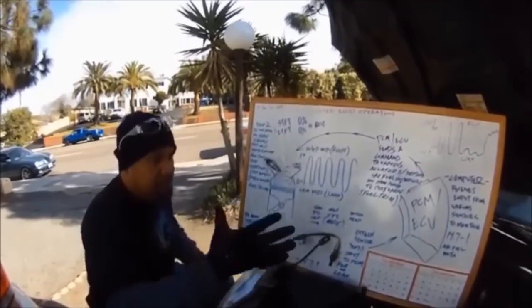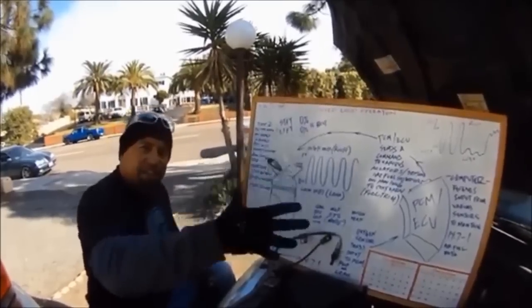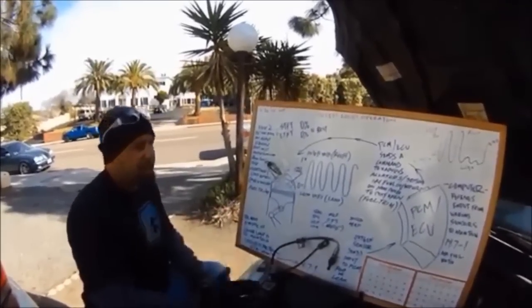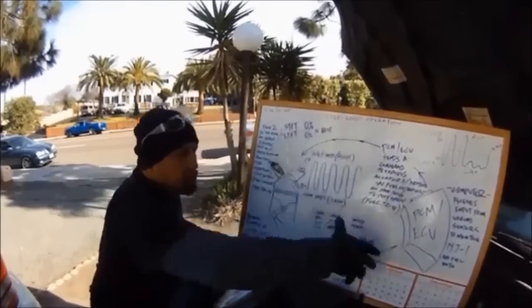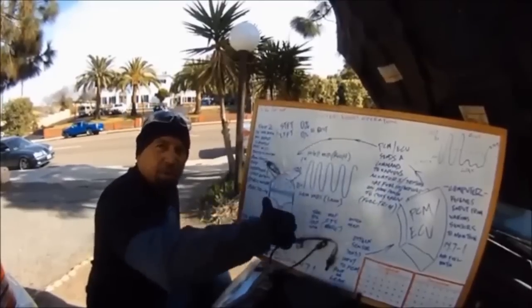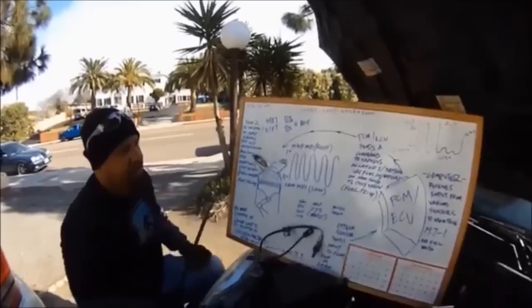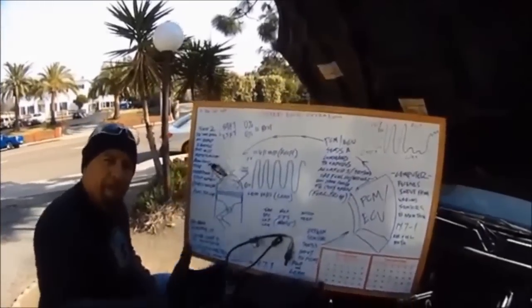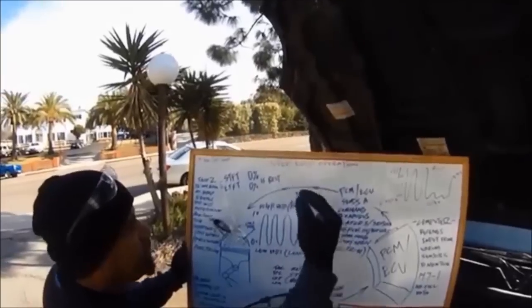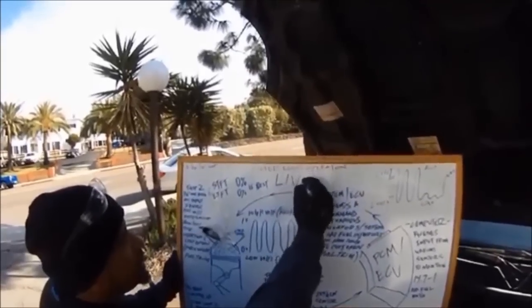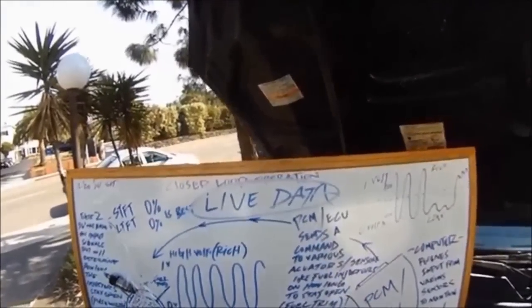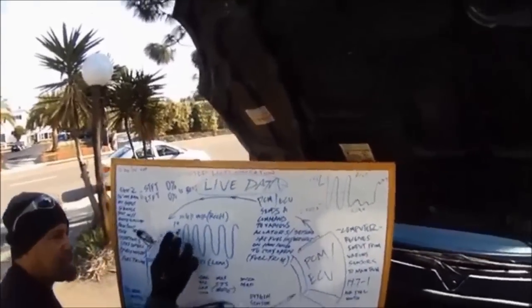You got to keep in mind, these cars are computerized engine control systems. And all of this is communicating. You need to know what's saying what. Why this is doing that. And it's that simple, man. Learn your fuel trims. If you're going to get a scanner, make sure you got this in there, man. Live data. Very important, man. Your scanner must be able to read this stuff.